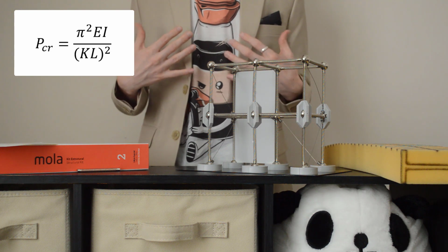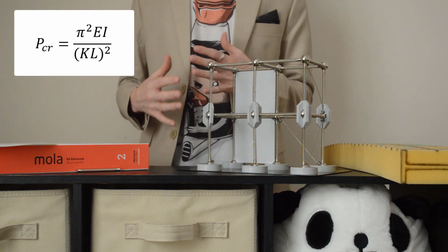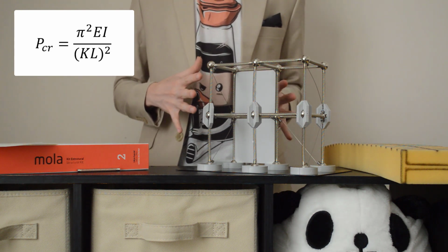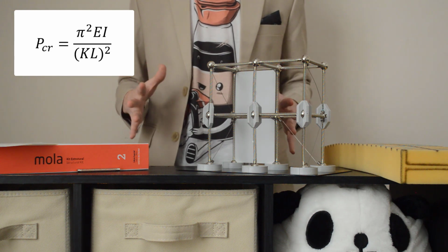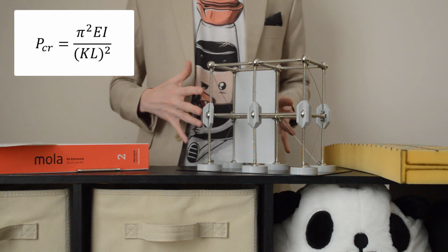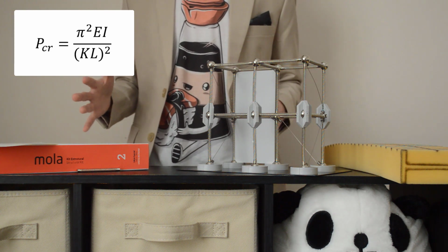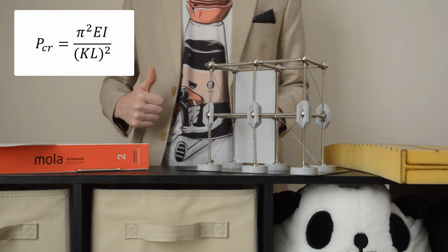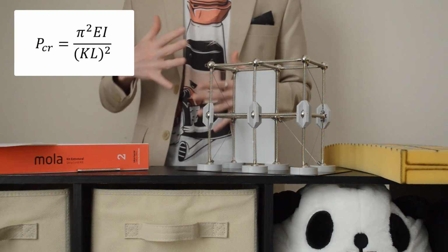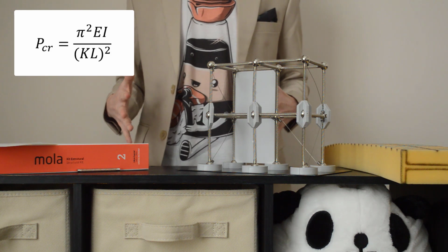As a structural engineer, our goal is to determine both the demand on a member and its capacity. If the capacity of the member exceeds the demand, then the design is adequate. If not, we need to change some parameters.